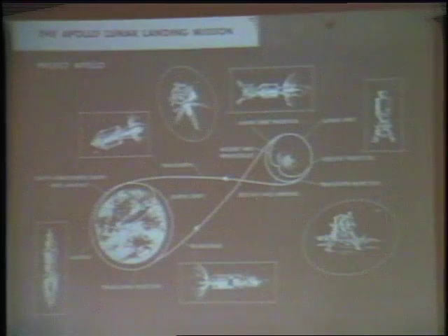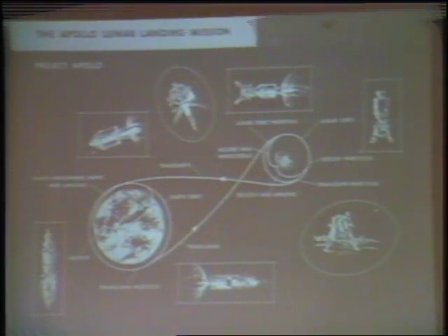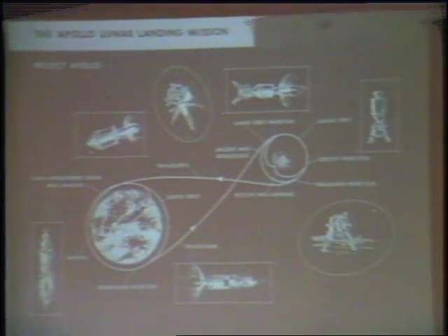That information gets put into the computer, and from that the computer computes what's called the state vector, which is the position and velocity of the missile at any point of time. And then it'll continue to update that as time goes on. So that's navigation. Then anytime there's thrusting, as shown in this point here and up here, over here, there's thrusting. That part is the guidance and control.